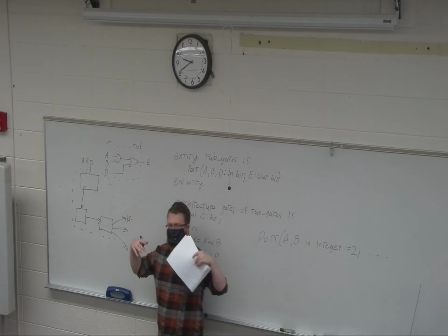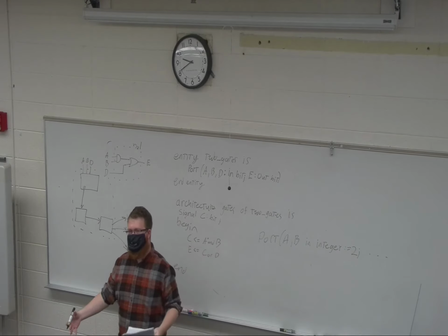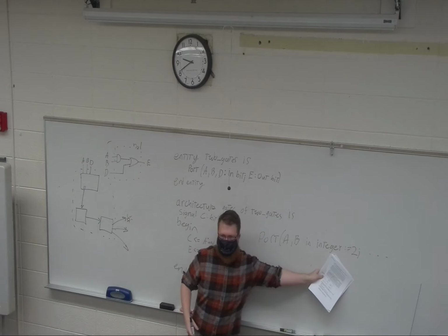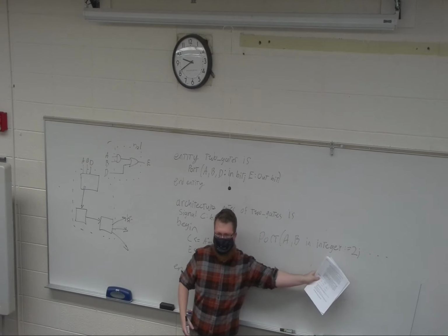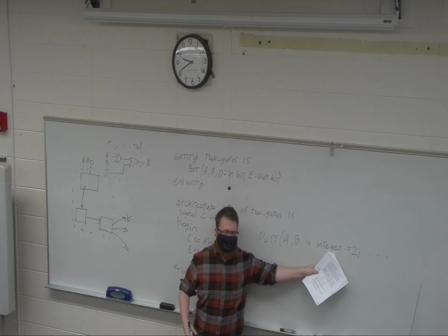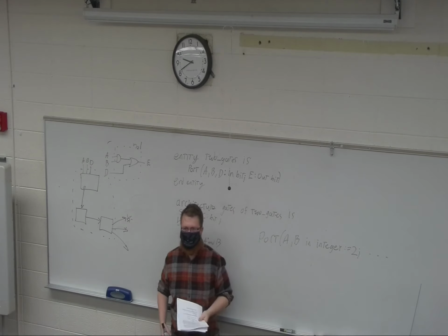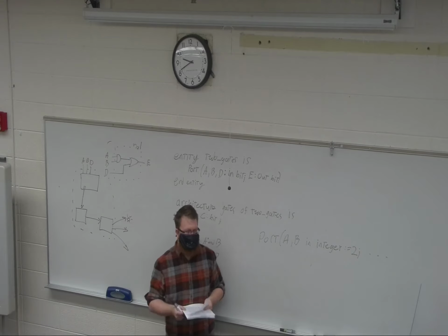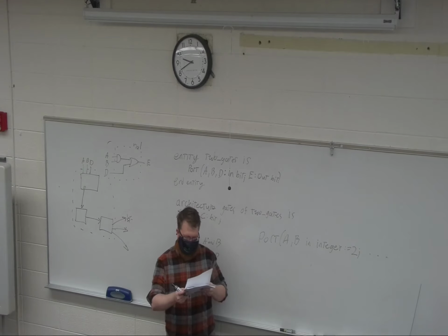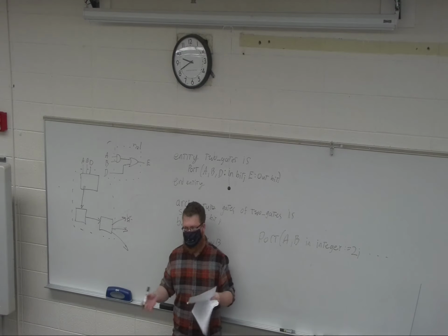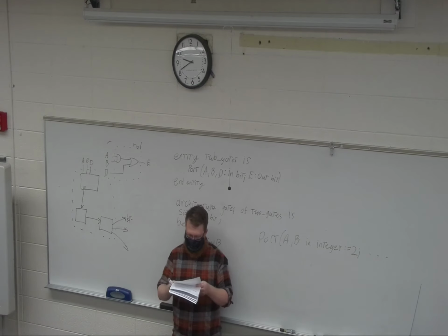What that's going to do is initialize the value to 2. However, again, not synthesizable. It works in the simulation, it does not make that true when you make the logic. Everyone got that? Yeah, so here's my note saying we generally restrict ourselves to in, out, and in-out modes, and mostly in and out.